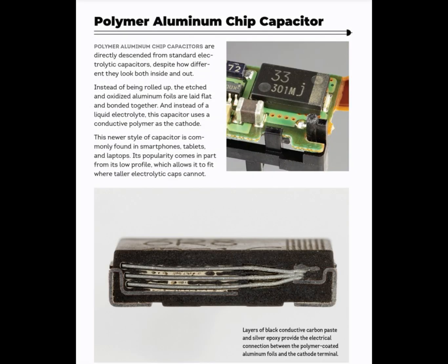Polymer aluminum chip capacitor. They are another type of capacitor that utilizes aluminum as the anode material and a conductive polymer as the electrolyte. They combine some of the advantages of both aluminum electrolytic capacitors and solid polymer technology. The polymer aluminum capacitors have lower ESR, low equivalent series resistance, than traditional aluminum electrolytics, making them suitable for high-frequency applications. They can handle higher ripple currents, which is beneficial in power supply circuits. These capacitors are available in small sizes, ideal for space-constrained applications.